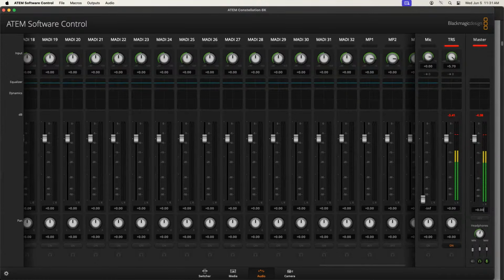Next question comes to us from Rion Smith in Trinidad, West Indies. What does the Mic+Plug in power option in the mixer settings mean? So yeah, if you're using small little electret microphones that use more or less 5 volts, that's what the plug-in power is for. Like, say, lavalier microphones. Little lavalier microphones, little gooseneck microphones are also electret microphones. So those little microphones that take 5 volts of bias power are what we require that plug-in power setting for.